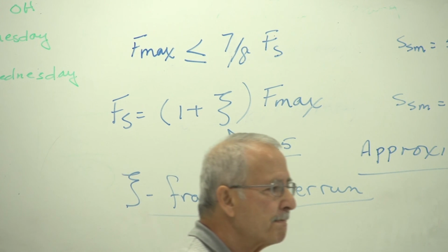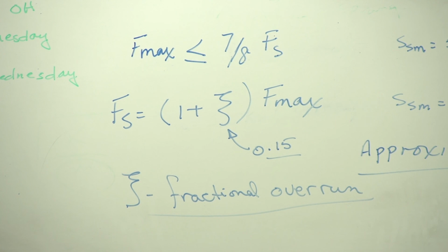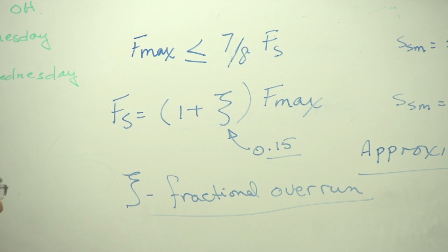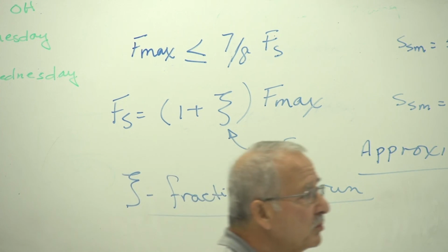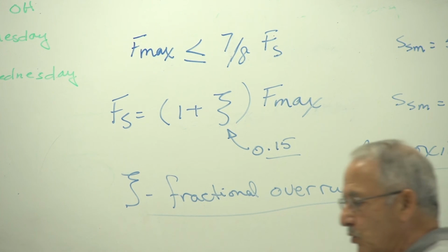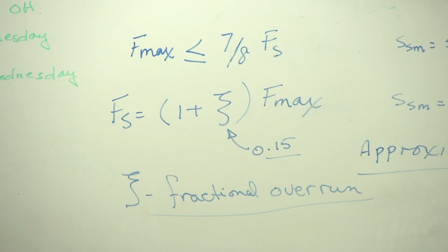Is it always going to be 0.15? No, that's what I was just saying. Your book says 0.15, which is fine. If you want to use 0.15, it's okay. But you will see that in one of the example problems, I'll be using 10%, 0.10. So it's 0.15 unless it's otherwise. Yes, yes. Or the problem may tell you. It may tell you the force at solid height should be 12% larger than the maximum load, for example. Then it's neither 10 nor 15, but 12. So, okay.